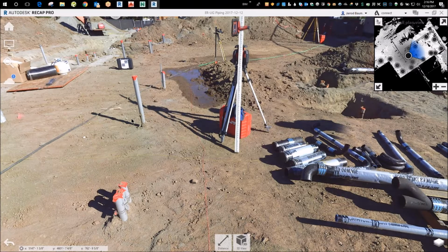We're going to do that pretty much on every job now, going forward. We've checked EHS, come out there with the total station, sync up, and then start shooting things to confirm. Are we anywhere close? I mean, lots of CMU is easy, right? Face of CMU is a grid line almost every time. So you scan that on survey control and bring it in, and you know right off the bat.